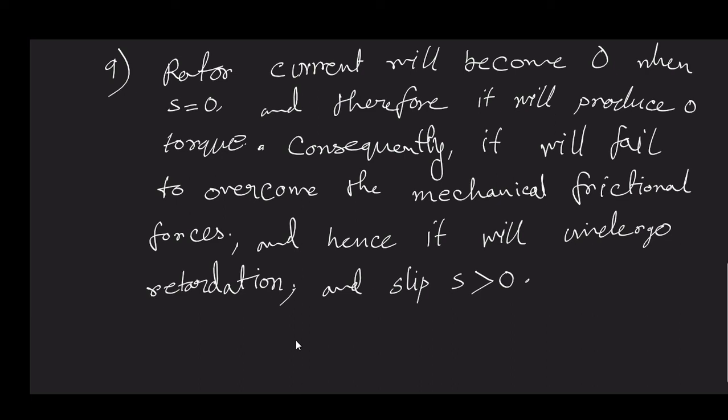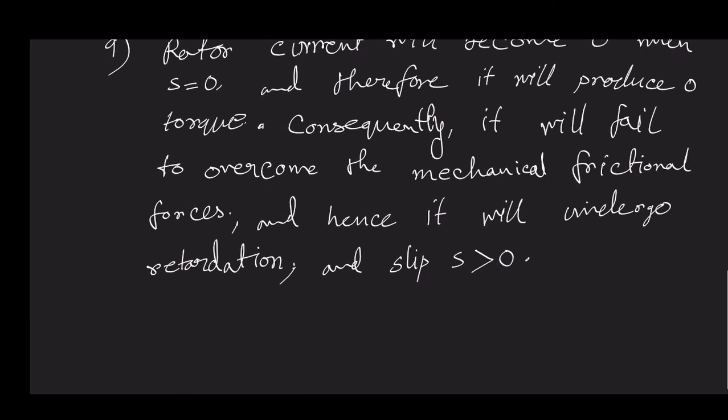Now, this induction motor's rotor can be viewed as the secondary side of a transformer, and the stator is like the primary side of the transformer. So what we can do is try to develop the equivalent circuit based on this.